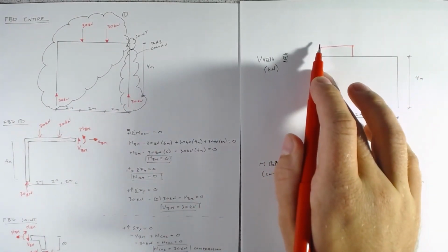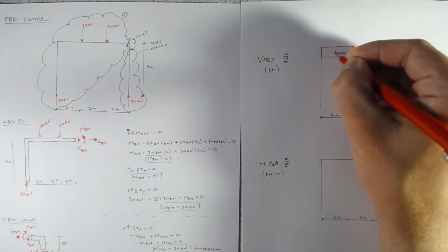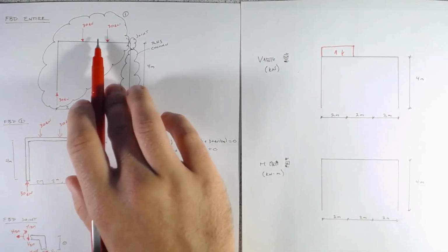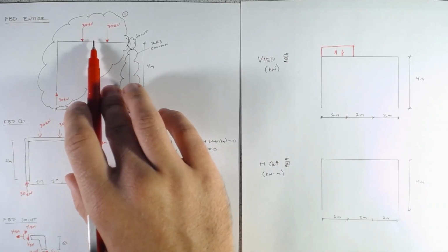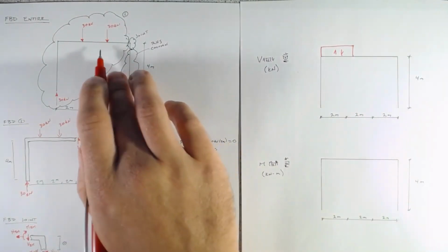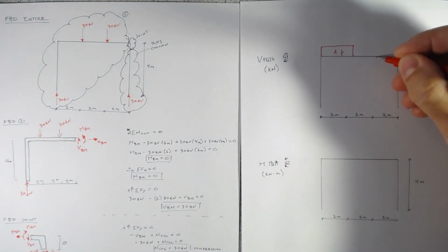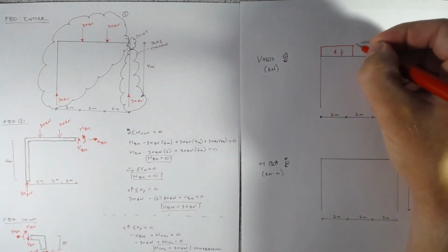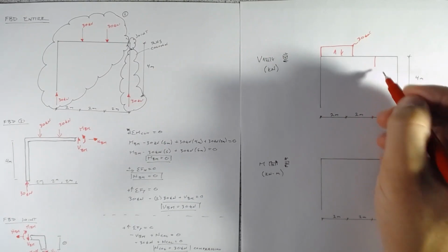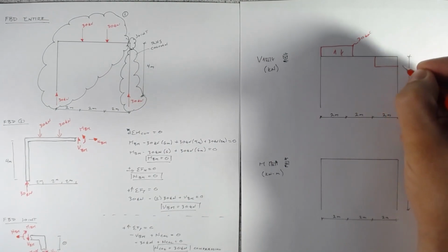So if we went up 30 kilonewtons of shear, and then we have a load of 30 kilonewtons down, that's what our shear is now. As we go across, again, the magnitude of the load is the negative slope of the line for our shear force diagram. So if it's 0, we stay at 0 until we get to our 30 kilonewtons, and it's going to push us down 30 kilonewtons. So I'll put it's 30 kilonewtons, and then we will go over, also 30 kilonewtons.